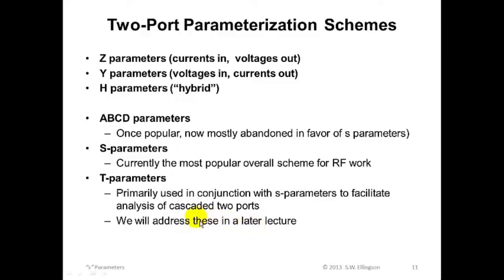These days, S-parameters are by far the most important and commonly used scheme for the parameterization of two ports at radio frequencies. One reason for this is that S-parameters, in contrast to impedances and admittances and hybrid coefficients, are relatively easy to measure at radio frequencies. And I'll show you some examples in a moment. We'll focus primarily on this approach of S-parameters, and subsequent lectures will assume that you are proficient in this scheme.